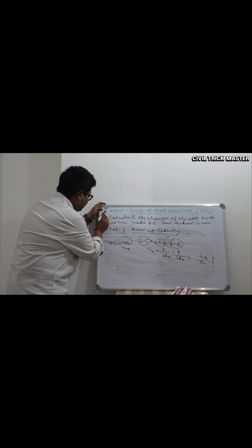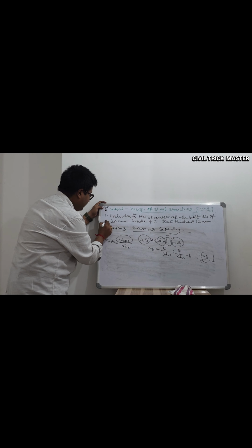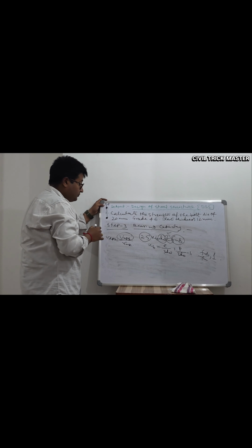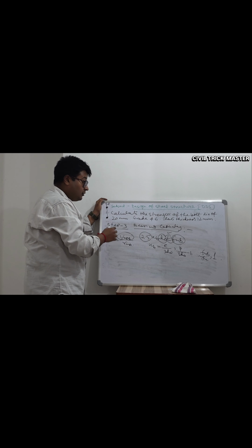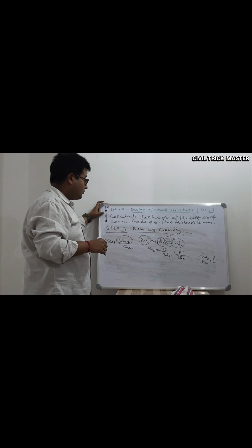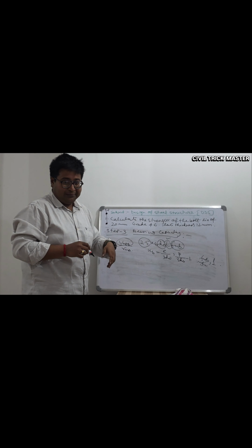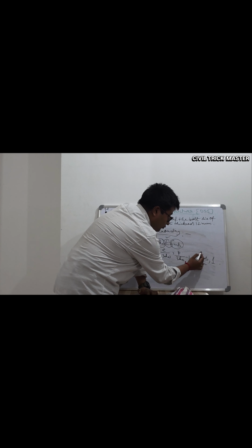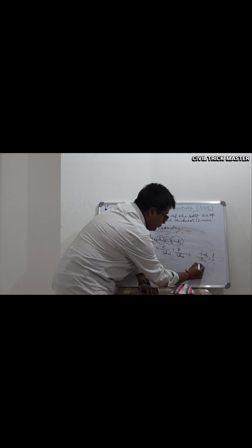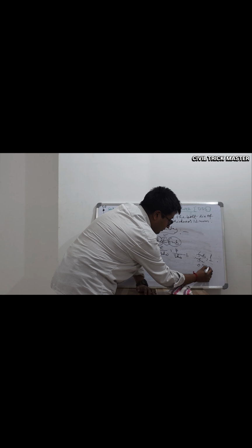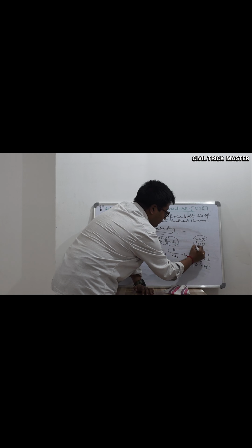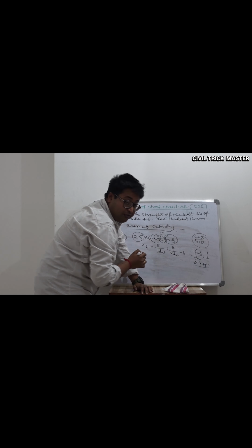If that is the first bolt and that is the second bolt, the distance between two consecutive bolts from center to center, that is called the c by c distance, the pitch distance. If we calculate fub by fu, 400 by 410, you will get 0.975.